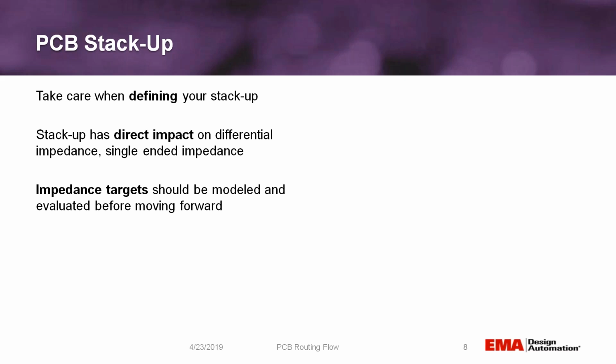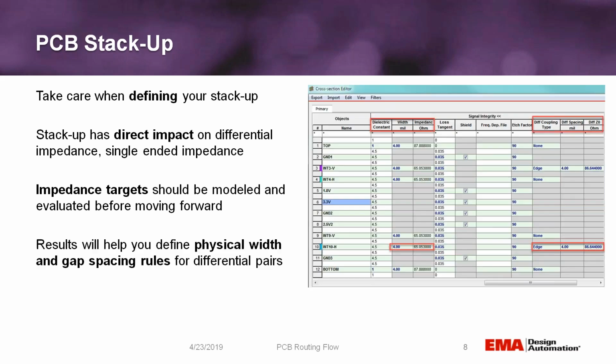This may entail working with your board shop, your fabricator, because they may have specific cores that they stock for a build. So you would always want to send your stack-up to your vendor and have them approve it, because they're the ones that are going to guarantee that your design meets the impedance requirements.